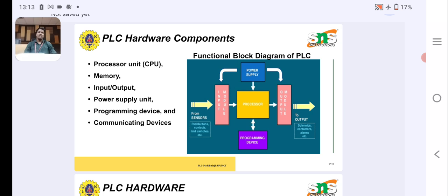In small PLCs, the address is often a number preceded by a letter indicating whether it is an output or input. Thus the PLC might have input addresses like X400, 401, 402, followed by outputs with the addresses Y430, 431, 432. These are things we have to follow while using PLCs.